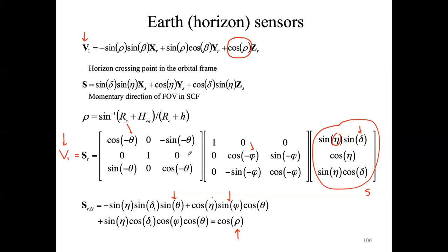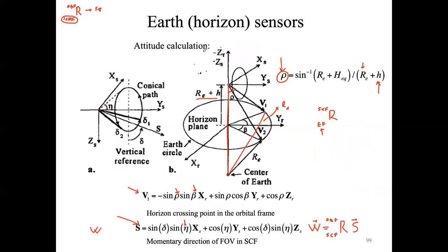So this only demonstrates that, in principle, the Earth horizon sensors is able to give you the attitude of the spacecraft by using, for example, three crossing points of the Earth horizon. So if you have these three crossing points, you will have enough equations in order to determine the roll axis angle, theta, the pitch axis angle, and rho. If you know rho, that will become indeed a known parameter, and so you have enough equations to determine the theta and phi angles. So this is only a very quick demonstration. If you want to use Earth...